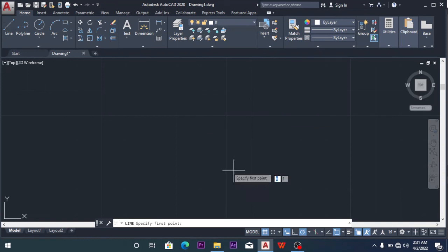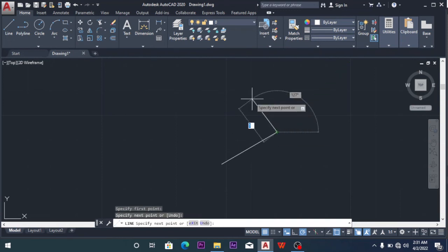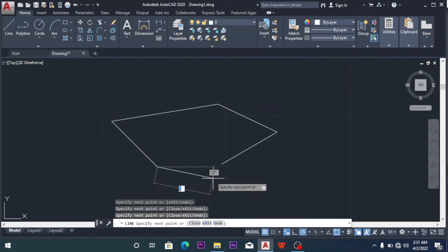Let's say, for example, I want to place this at an angle of 37 degrees, 30 degrees. I click, and the same thing happens, just at any angle you want. That is the use of the polar tracking, unlike the auto mode, which only draws vertical and horizontal lines. So the polar tracking helps you to draw in any direction you want.